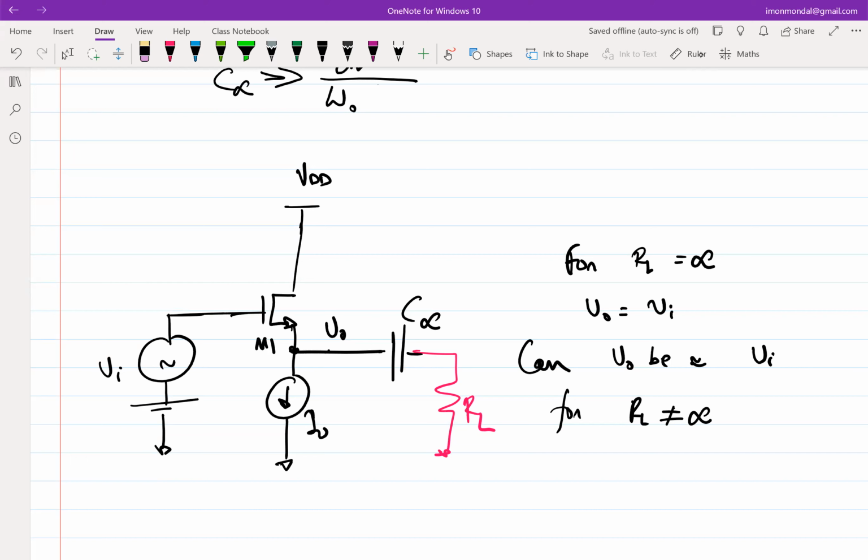So essentially the question that I'm asking, without really using the technical term, is: is RL loading your structure? RL equal to infinity means RL is not loading. I am asking, is there a range of RL for which it doesn't load? So now you should be able to immediately say, when I'm asking if RL is loading or not, what are you going to test?